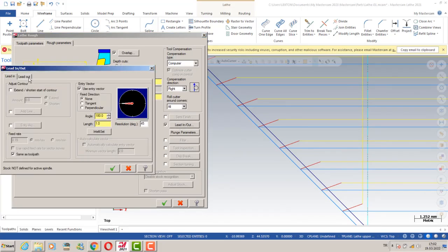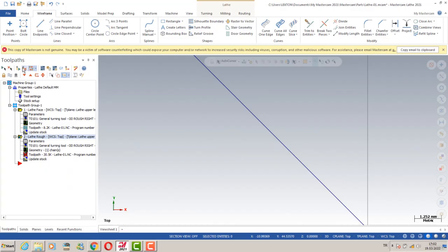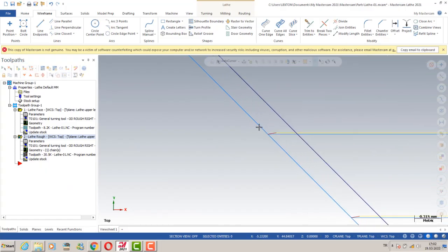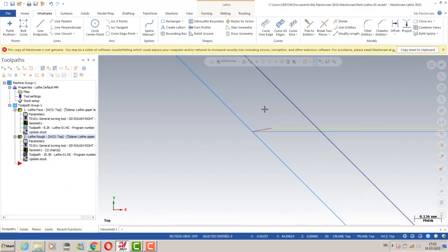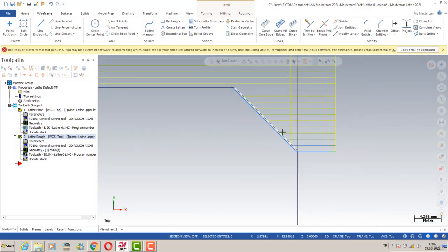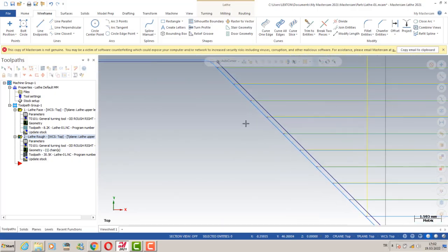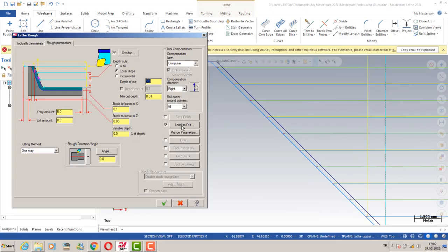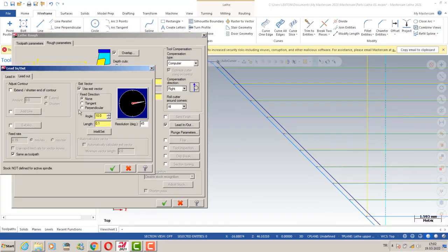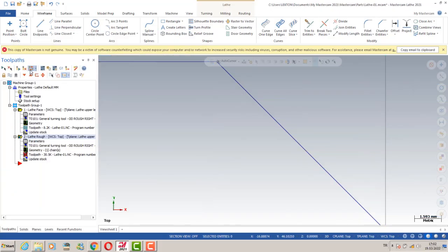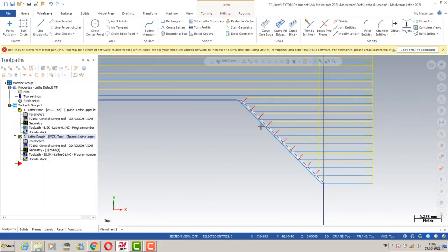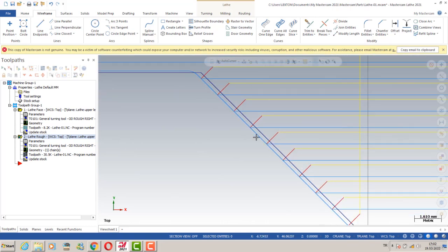If you would like to optimize your toolpath, you can write 0.5 millimeter with 10 degrees. That's only our retract position like this. Maybe you should also think about that. Let's go back to the default values here, 1 and our degree.